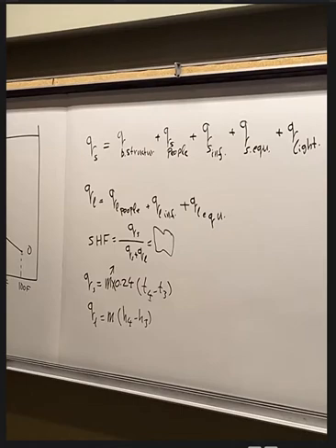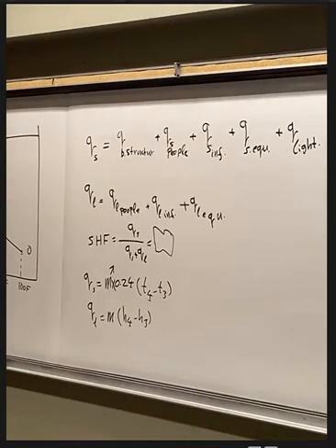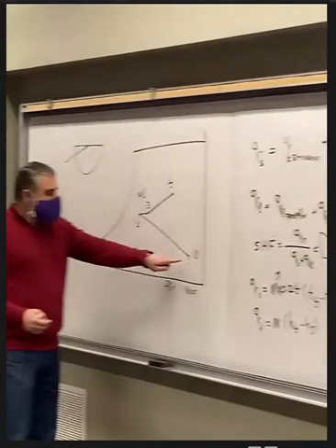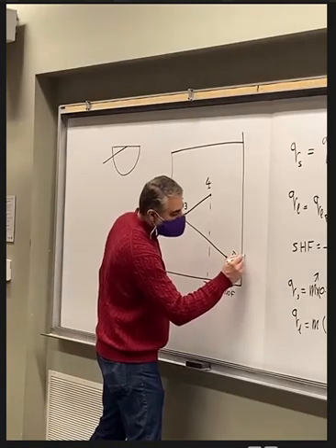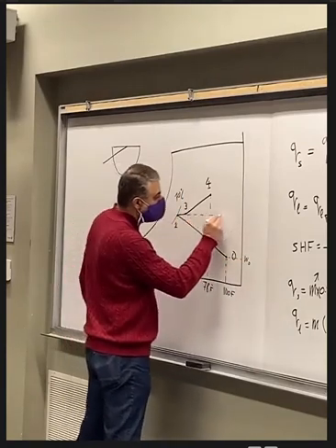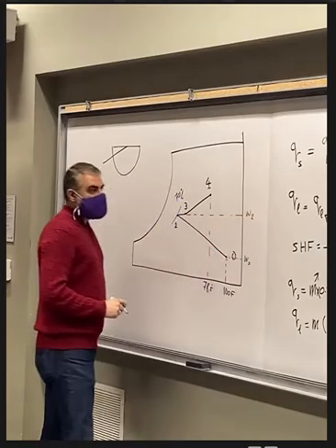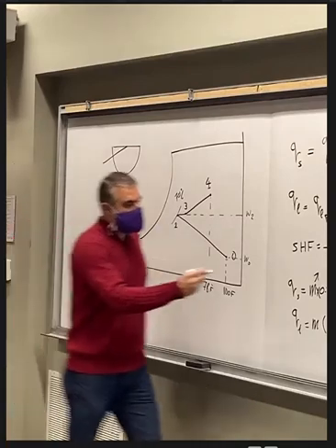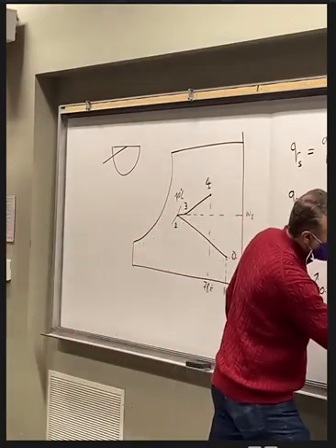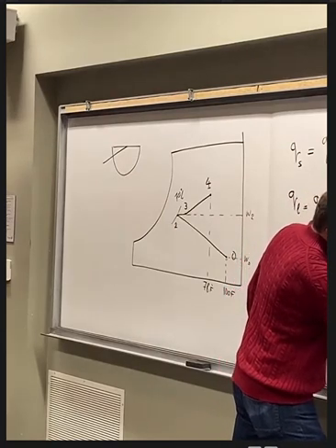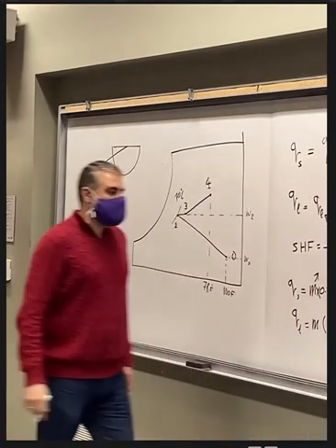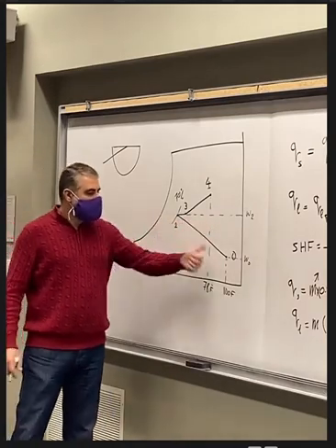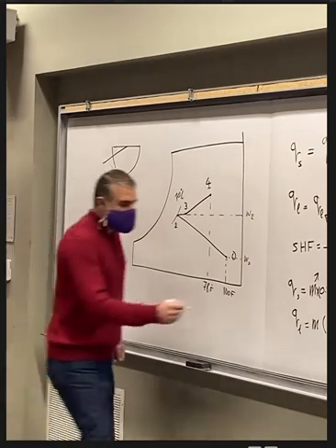So now we need to find the flow rate of the water in the adiabatic humidifier. The air enters the humidifier at point 0 and leaves at point 2. So we have W0, and we also have W2. In this case, MW equals MA multiplied by W2 minus W0. We know both W's, and we know the mass flow rate of the air, MA.